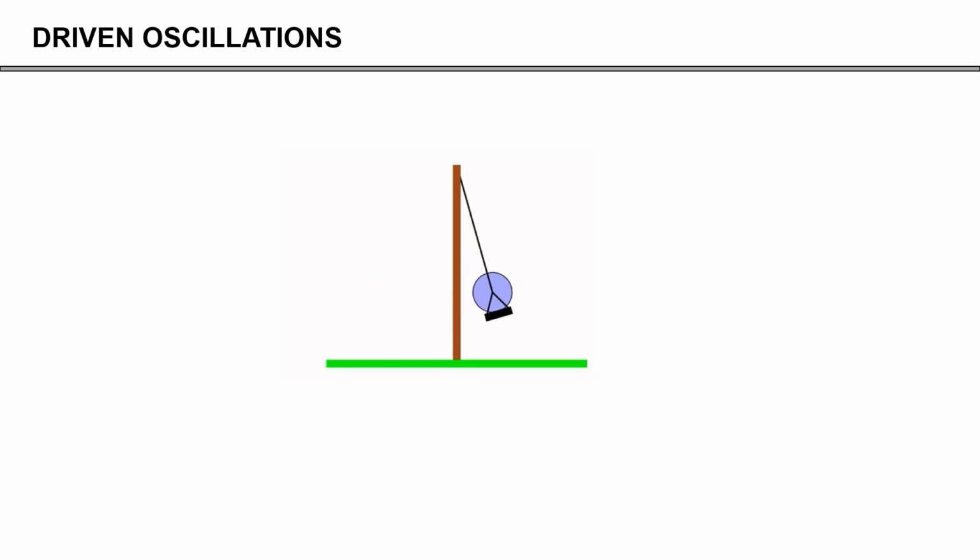In other words, the higher the Q value is, the less resistance there is, and the smaller this little tap can be to get a really large effect. In terms of an RF coil, the higher the Q value of the RF coil, the less the input voltage needs to be for a significant B1 field to be created by that RF coil.